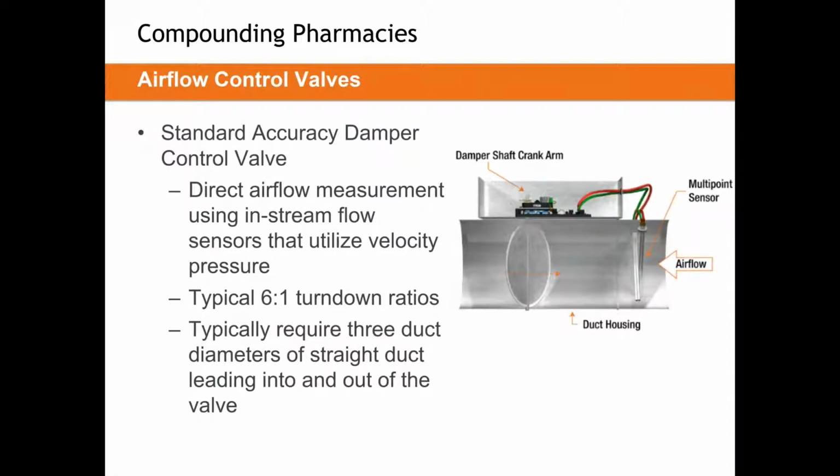Low numbers, like a low pressure, are very difficult to measure, meaning it's very difficult to control a VAV box to a very high accuracy and a very high precision point. No manufacturer will typically claim that the entire VAV box has been tested and can be controlled to plus or minus 5% accuracy. And that's the number I want to lean on here a little bit.